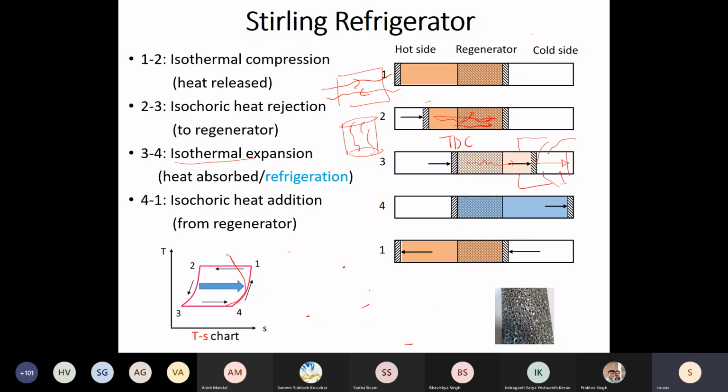And then similarly, a very small amount of gas would be cooled in the porous media, and then the majority of the cooling will happen when you expect heat absorption. So maybe only this much cooling and this small amount of heating will happen in the porous media, whereas you expected to have this. So the faster you go, the worse your regeneration will become. So these heat exchangers are called regenerative type heat exchangers.